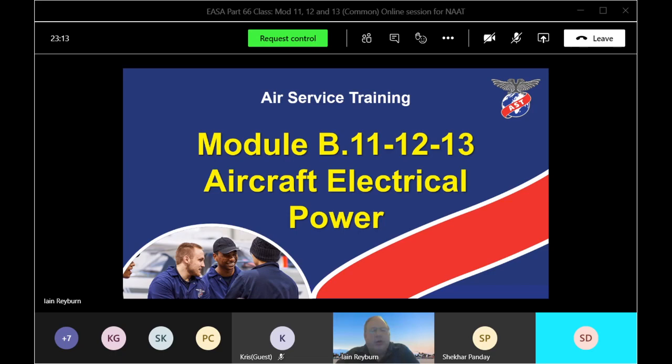Yes, okay. So just remember that all we're doing is changing the average time that the excitation is on. So again, if it's a low voltage, it's a larger time on. And in the old analog system, if it was a low voltage, it was a larger voltage. So the larger hasn't changed. Okay, so that's how we control excitation in a digital or solid state voltage regulator.